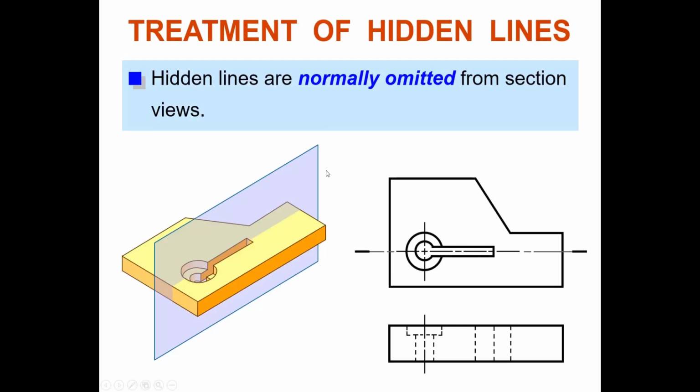For straight cutting, full sectioning, class, full sectioning does not mean in the middle or the center axis. No. Any feature with just a straight cut, any portion of your part, maybe in the middle, maybe at this axis of the slot, is a full section. This one is offset section. But here, with one straight cutting plane, we can describe the internal structure of the C-bore and the slot. Clear? Guys, I hope you understand.